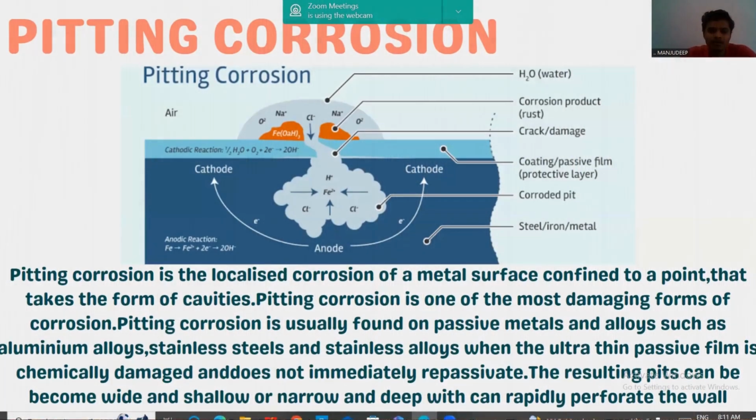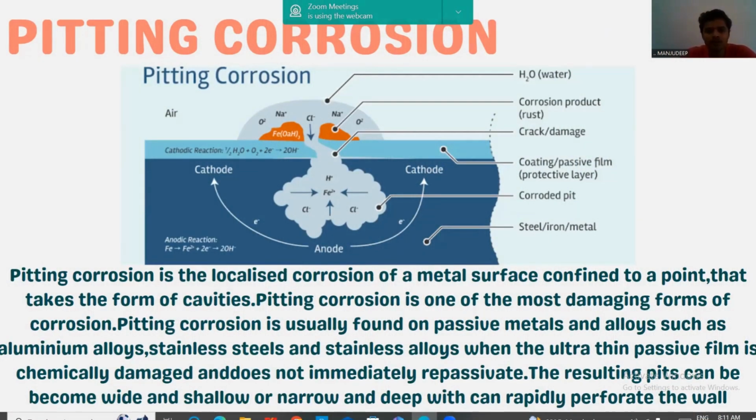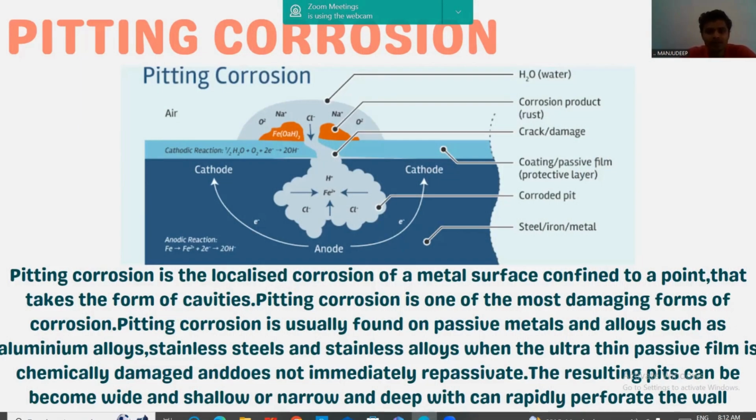The metal surface with less oxygen concentration will act as the anode and oxidation will take place, which leads to corrosion, whereas the other surface in contact with more oxygen will act as the cathode, where reduction takes place, and is unaffected by corrosion. In pitting corrosion, small pits are formed in the area or surface where dust or oil droplets have been deposited.